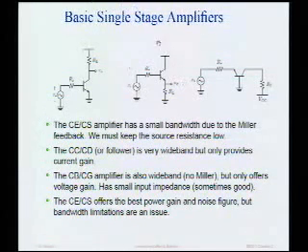Okay, so how about a source follower? What's the problem with the source follower? Well, the source follower is a nice amplifier. One of the issues is that it has a very high input impedance, and actually it's an issue also with the common source amplifier, which we didn't really talk about. We'll learn about that later. It's hard to match the input if you're trying to get a matched input impedance. But as you can see, a source follower also doesn't have voltage gain, right? In fact, it has voltage gain roughly equal to 1, but it has lots of current gain.